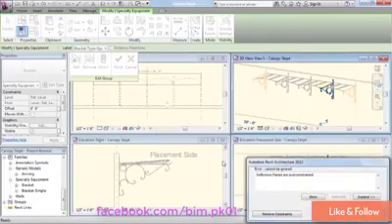Now, unfortunately, when I do this, Revit is going to generate an error, and these are the kind of errors you don't really like to see because they cannot be ignored. So some of these errors are relatively benign, and you can ignore them, or they give you a few possible remedies. This particular one, you have to deal with it before you can continue. Now, neither option that they're offering is really terribly great. You can either cancel, which basically stops the whole command dead in its tracks and we can't continue, or we can remove constraints.